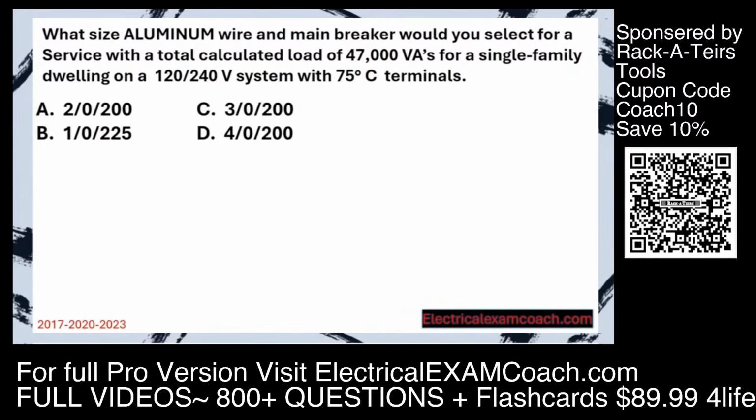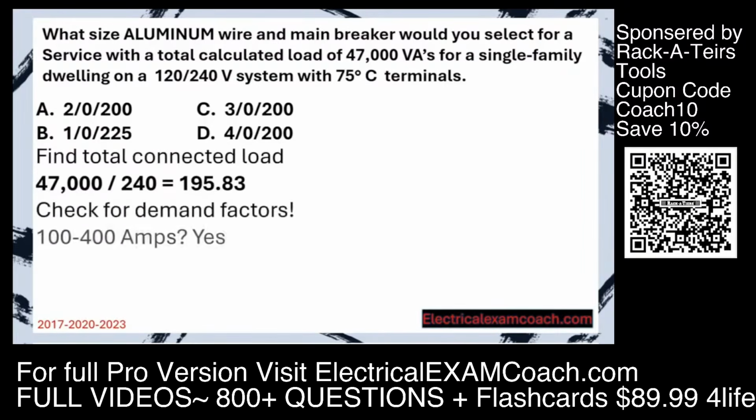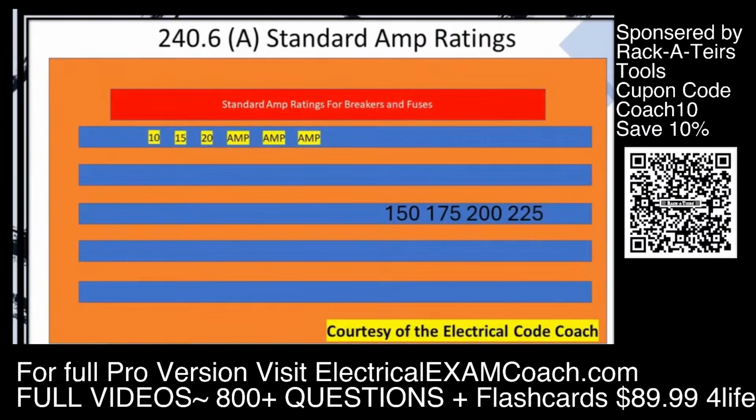What size aluminum wire and main breaker would you select for a service with a total calculated load of 47,000 VAs for a single family dwelling on a 120/240 volt system with 75-degree C terminals? Step 1, we're going to find our total connected load. In this case, they've given it to us, and we're just going to divide, just like we did before. Now, we check for demand factors. Is this in between 1 and 400 amps? Yes. Is this on a single family dwelling or the individual unit of like an apartment? Yes. So, the 83% rule does apply. And we're going to go size our overcurrent protective device. We end up putting it on a 200 amp breaker, just like we did before.